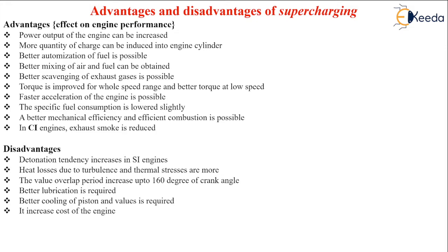Once again, better scavenging of exhaust gases is possible. Scavenging means removal of exhaust gases from the previous cycle to make room and give better chances of combustion in the next cycle. If compressed air is inducted into the combustion chamber, then this high pressure air will make the exhaust gases from the previous cycle move out of the combustion chamber in a more effective manner.